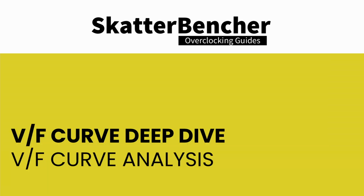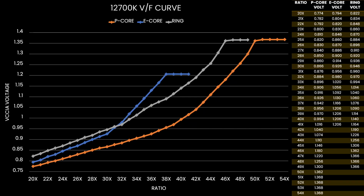To end this deep dive into the Alder Lake VF curve, let's have a look at the curves and do some analysis. There's a couple of things I want to highlight. First, for all VF curves, you can see there's a factory fused curve up to the maximum default turbo ratio. For the P-cores, that's up to 50x. For the E-cores, that's up to 38x. And for the ring, that's up to 46x. Higher ratios, by default, revert to the voltage of the highest predefined point.